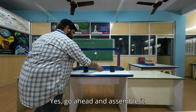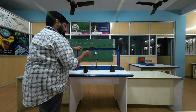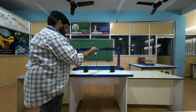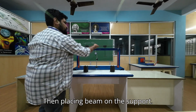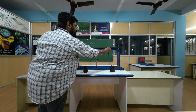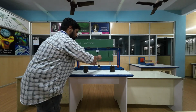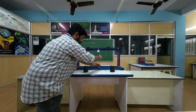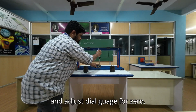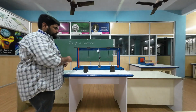Yes, you can go ahead and assemble. First weight hanger. Then placing beam on the support, position the weight hanger. Right. Next, dial gauge. Fix the magnet and adjust dial gauge for 0. Perfect. Okay, dismantling.